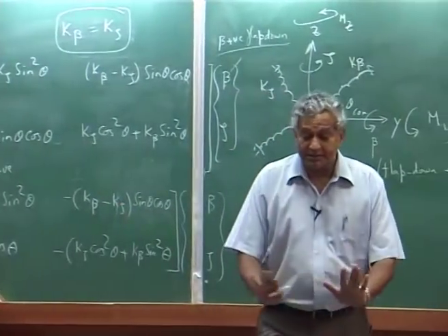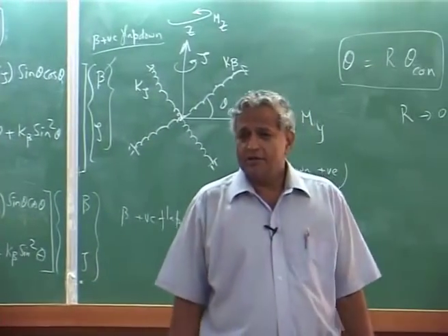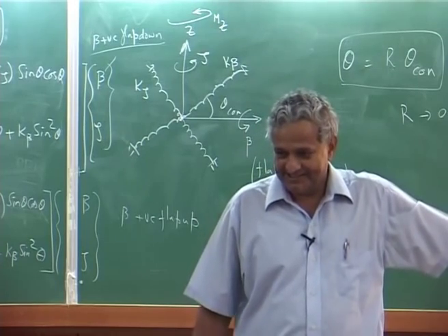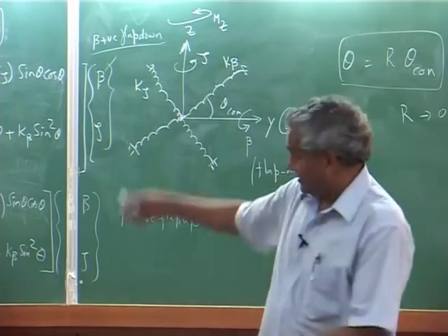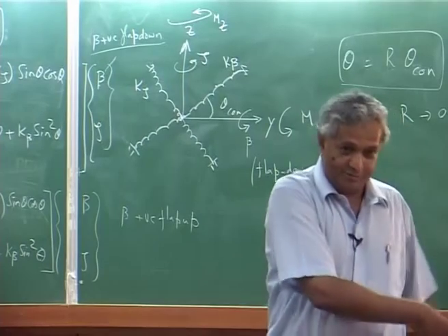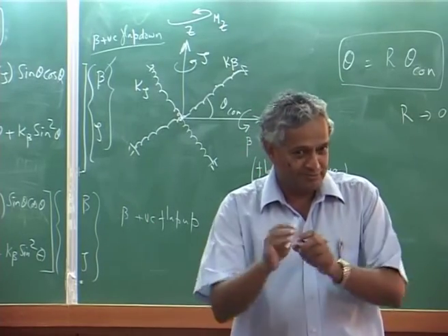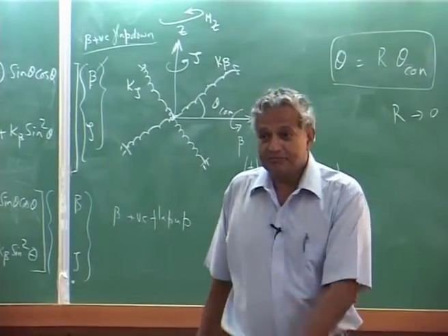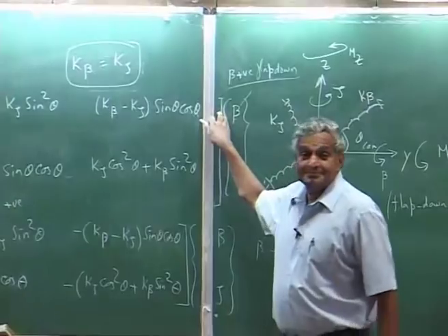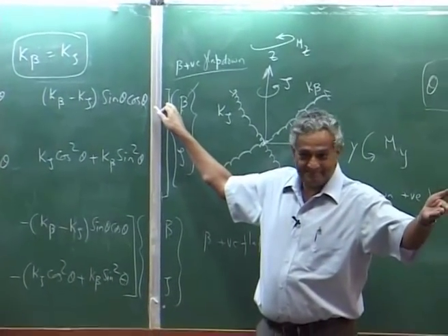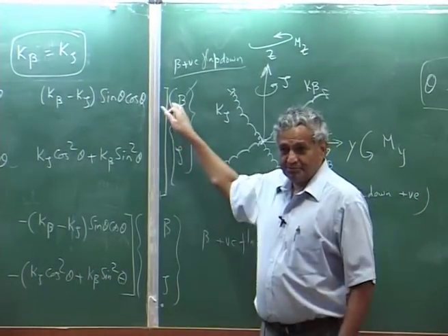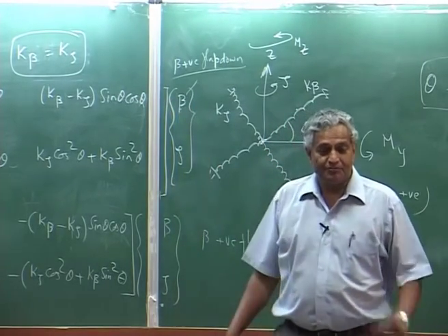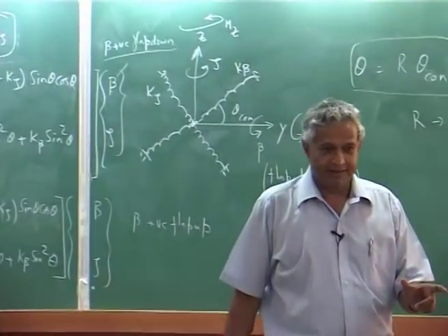Now you know automatically I can't analyze only flap motion, because the moment I have flap I get a lag movement, which will make the blade go lead lag, and if I have any pitch associated with that, then that will create a problem, and then lead lag motion will come and give me a flap deformation, okay, because these two are coupled. If I have lead lag, I will get a coupling to flap. So, flap and lag motion cannot be decoupled.